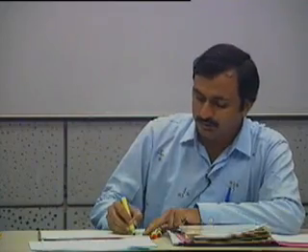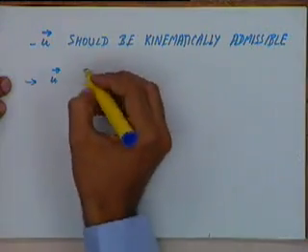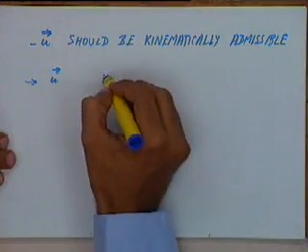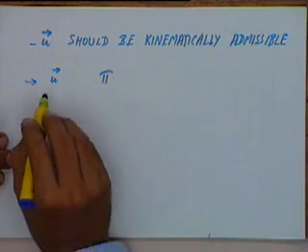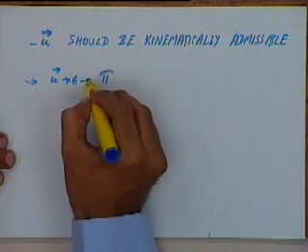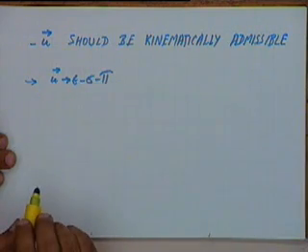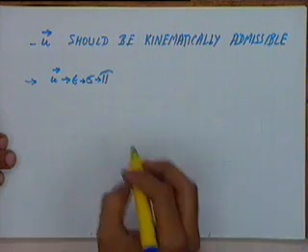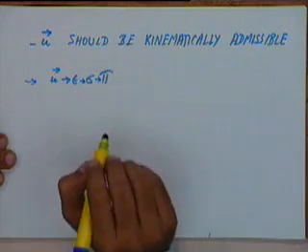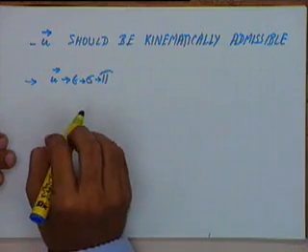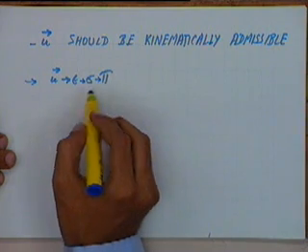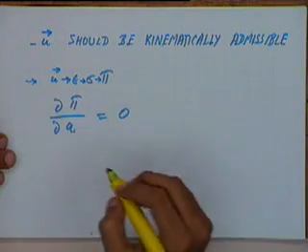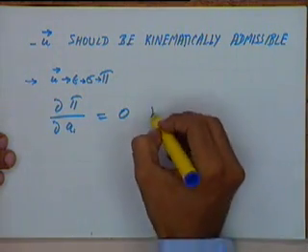Now once I have assumed u as a function of the phi's, then I can compute my potential energy. Because from u I will get epsilon and I will get sigma, and then I can compute the potential energy. Once I know the expression for the potential energy, then we will make use of the fact that under equilibrium the potential energy should be a minimum, which means that del pi by del ai should be equal to 0, for all ai.